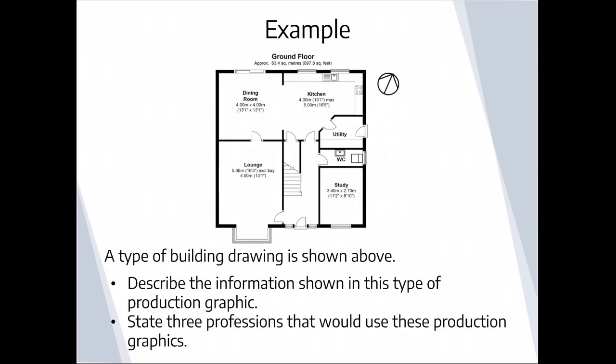There's a range of information shown in this floor plan. The dark, solid black lines indicate where walls are. The curved lines indicate where doors are positioned between rooms. It also shows windows, it shows where a staircase is. Also indicates sizes and dimensions of rooms and the names of those rooms, as well as other features like sink tops, hobs, toilets and wash hand basins. It gives critical information which is well proportioned, it's accurately positioned and sized, and it gives a clear indication of what that building will be laid out like.